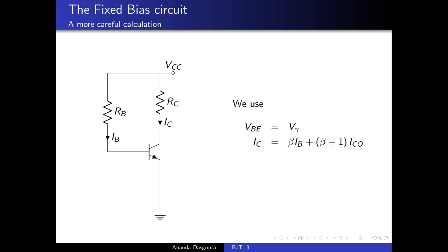The reason why we can do that is that in the common emitter configuration, the ground point or the reference point is the emitter, of course, and in order that the transistor be in active mode, the base has to be positive with respect to the emitter. This, of course, is for the NPN transistor, and the collector has to be positive with respect to the base, which means it also has to be positive with respect to the emitter. So here, compared to the common reference point, both the base and the collector are positive. So you can actually achieve that using a single battery.